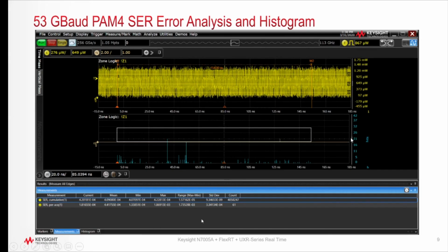Another way a designer can examine the error location and time relative to the start of a test pattern is to configure a horizontal histogram over the error distribution, which will clearly map the points of deterministic and random error locations in the pattern. Again, this is an ideal opportunity to increase equalizer complexity in a prescribed manner if the observed error rate is too high. Conversely, it offers an analytical means of dialing back an overly complex equalizer if it's exceeding the error rate requirements for a link.